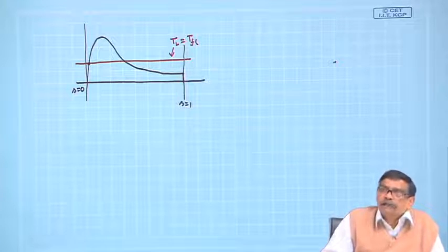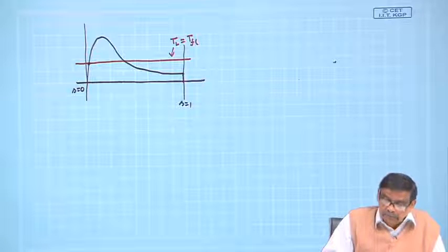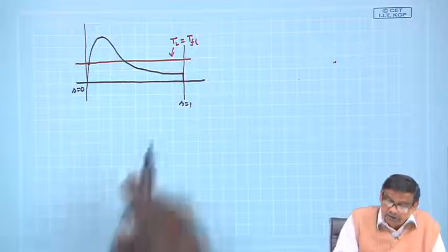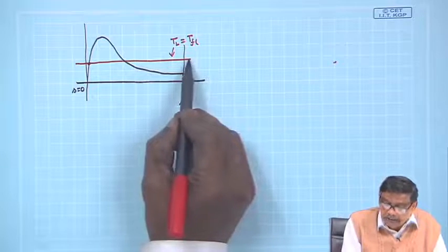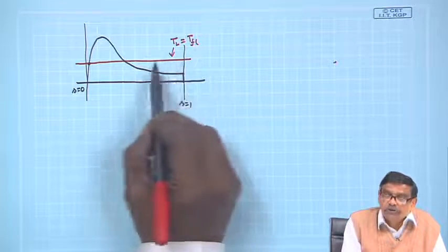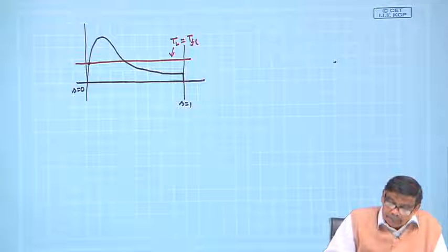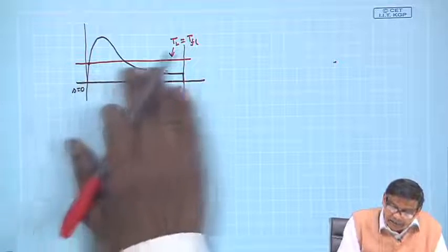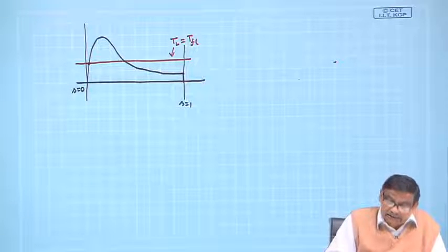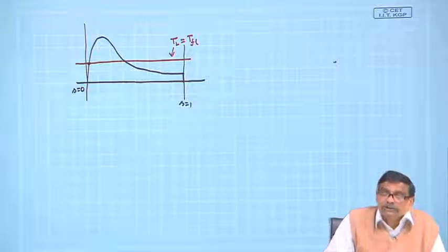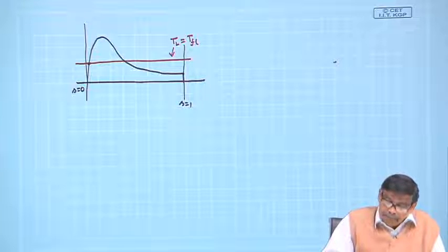Therefore, the motor will fail to start, because you have not produced enough starting torque to overcome the opposing full load torque which is already present. Okay? Therefore, this machine cannot be started as it is with full load mechanical torque connected to the shaft.